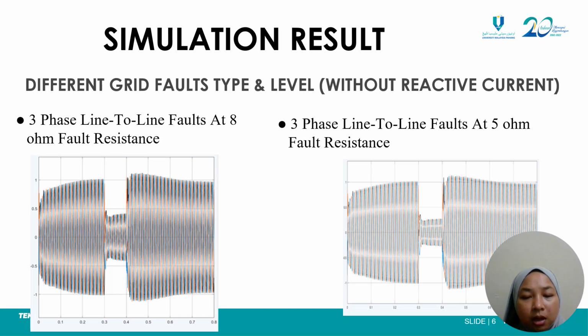respectively. This is because during a line-to-line fault in the three-phase power system, the voltage decrease is caused by a short circuit between two or more phases. This fault condition results in an abrupt increase in current flow and a significant drop in voltage. The defective phases become electrically connected when a line-to-line fault occurs, resulting in a path with low impedance.